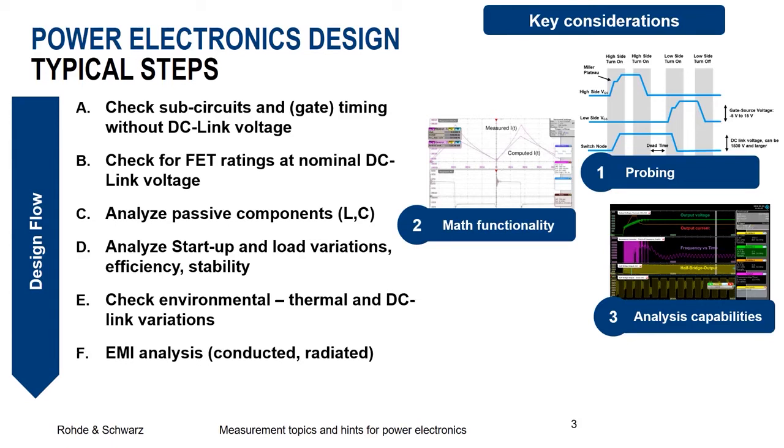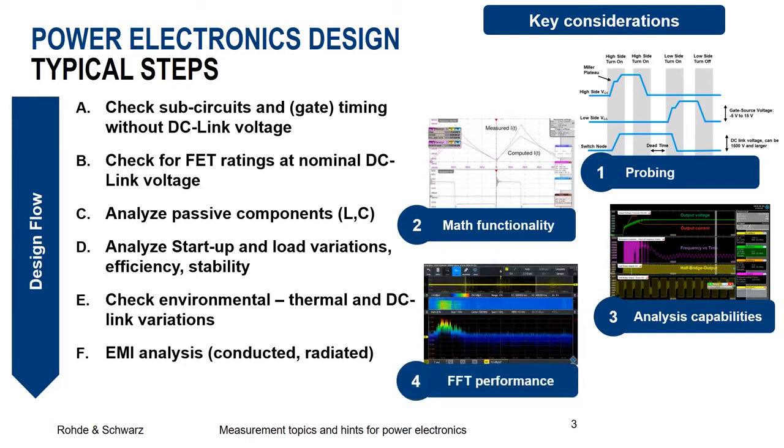Last but not least, going to EMI analysis, it's important that the oscilloscope one is using is also capable regarding FFT performance, because then you can already analyze EMI topics on the R&D designer's desk without the need to move to some dedicated pre-compliance setup, and do optimization work or design work already there.